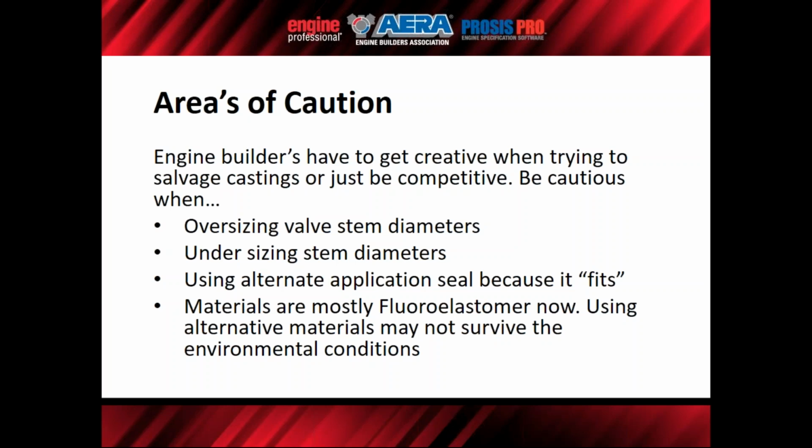Well, maybe that lip design was designed for a push rod engine, and you're trying to use an overhead cam engine. Again, as I said earlier, if that thing is standing in oil or completely submerged in oil, then the results can be drastically different, even though, hey, same stem diameter, it should work. So just keep those things in mind. Be cautious.